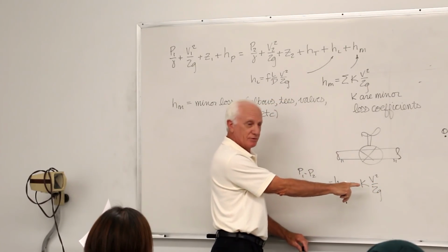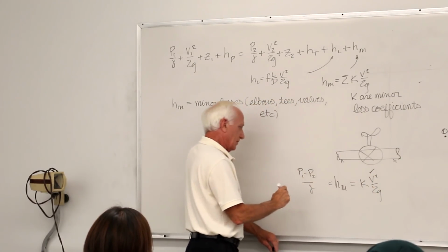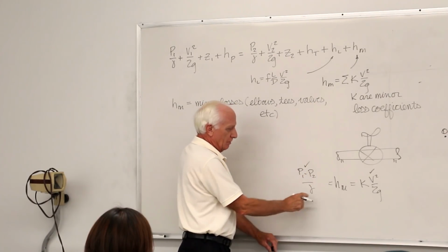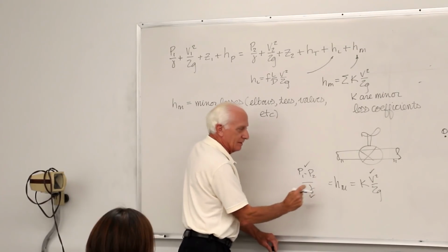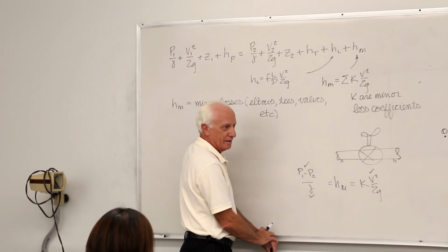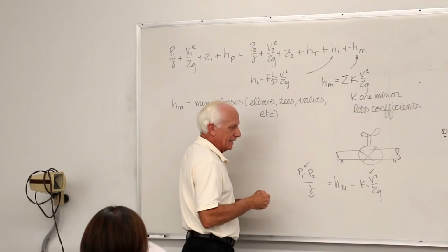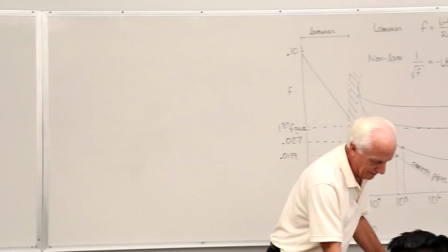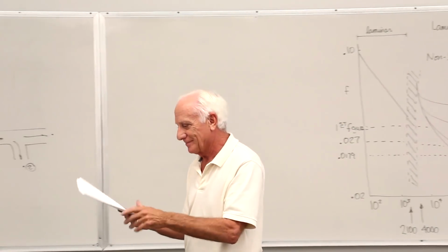You measure the velocity with the flow meter, I've got it. You measure delta P with a pressure transducer, I've got it. You know it's water at room temperature, I've got it. What do you solve for? K. The K values in that table came from that method of experimentation. So anyway, they came from experiments.